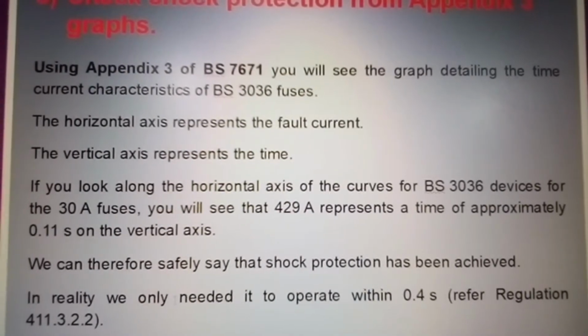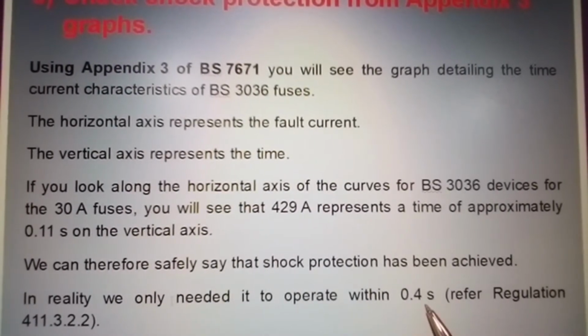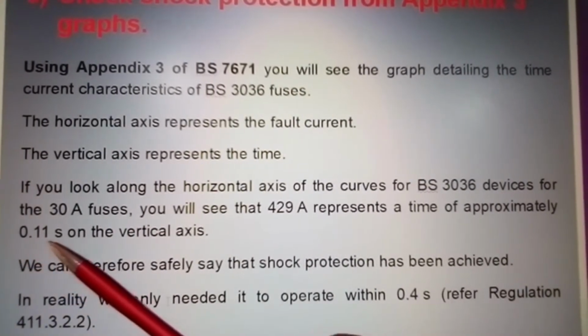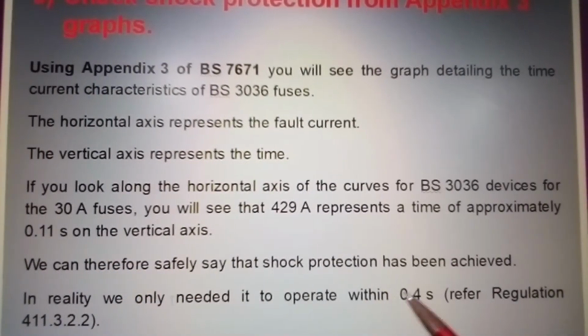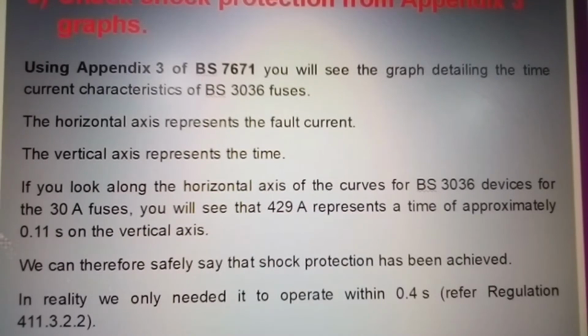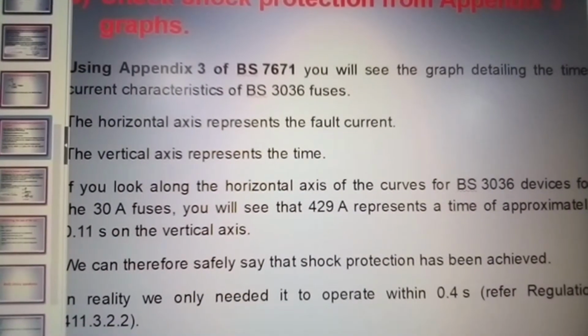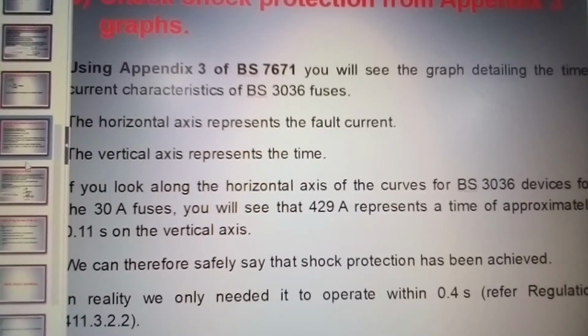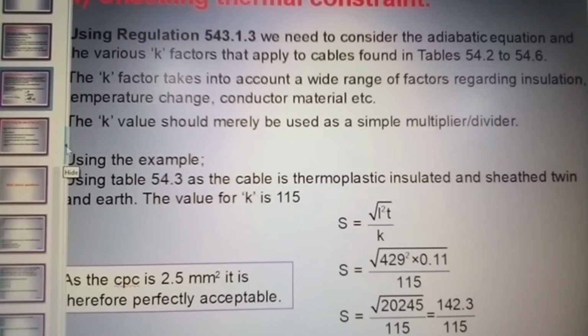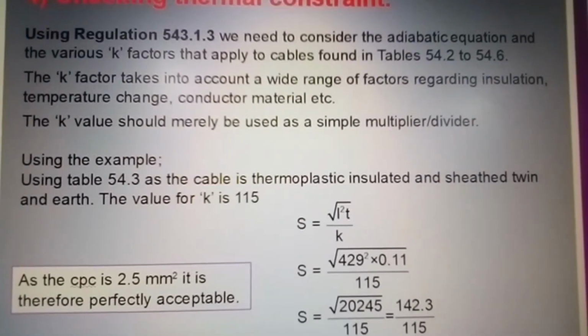So here is our operating time within standard format. 0.4 seconds we need to operate it in, and it's operating in 0.11 seconds, so we are well within our criteria. Now write these out for yourself. Look and read the information. Now checking for thermal constraint.